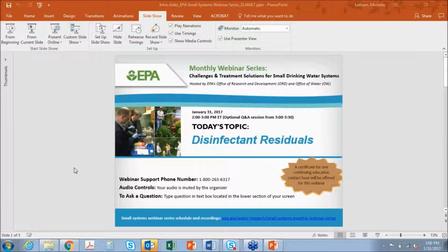Okay, thank you very much, Jonathan. What is the best method for testing chlorine residual in water systems with ammonia in the raw water? What are the best practices to get consistent results? That's a good question, and it really depends on where you are in the breakpoint curve, and that gets to how much chlorine you've added, and it gets back to also what concentration of ammonia you have in your raw water. So if you've achieved breakpoint, you should have predominantly just a free chlorine residual.